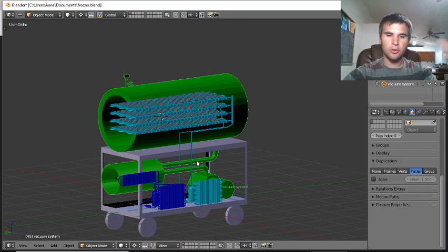tubing and the longer tubing will actually have a massive impact on slowing down the process of vacuuming the system. In fact, in my drawing here, where I've got these two big long lengths right here and right here, that would not be desirable. We'd want to either move the pump closer or move the cool chamber back more in reality to keep these pipes literally as short as possible. Same thing with the height. You'd want all of this to just be as short as possible.